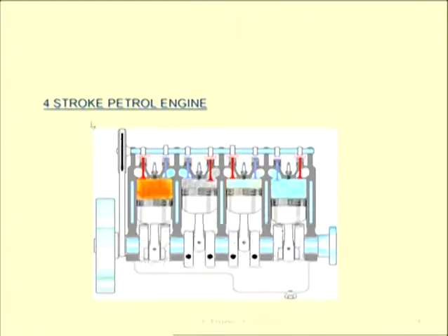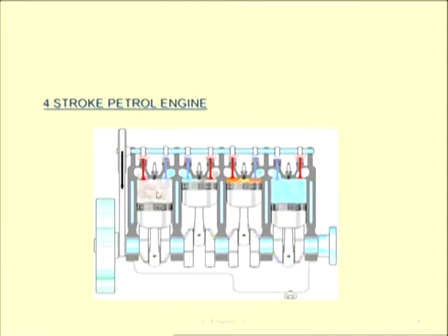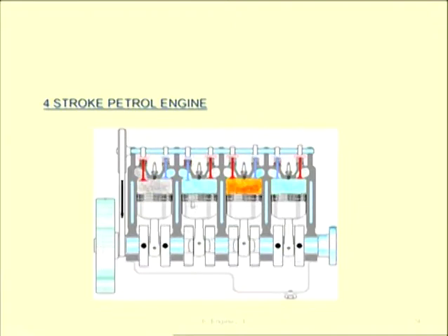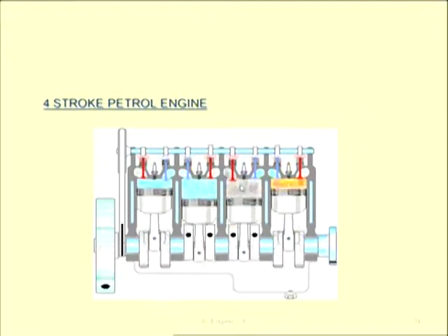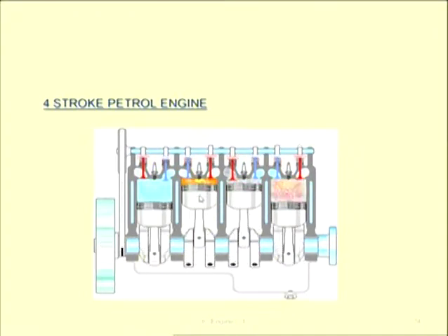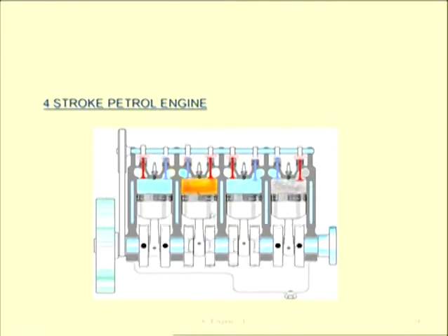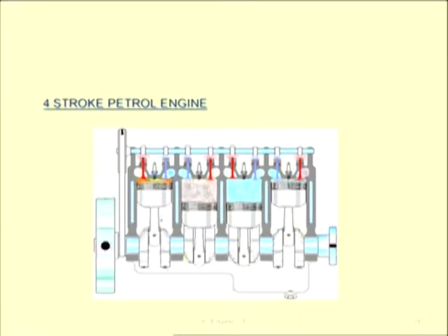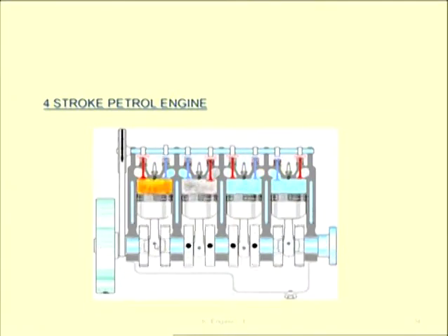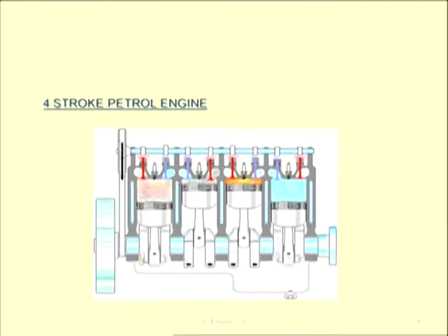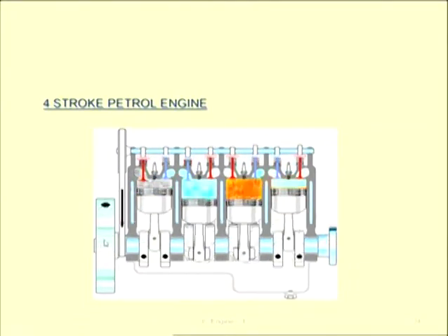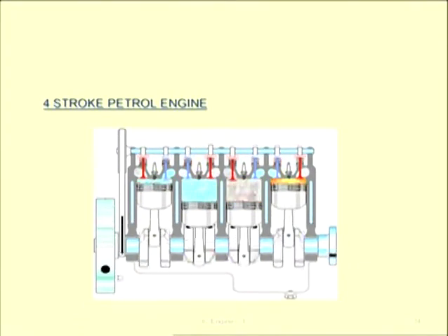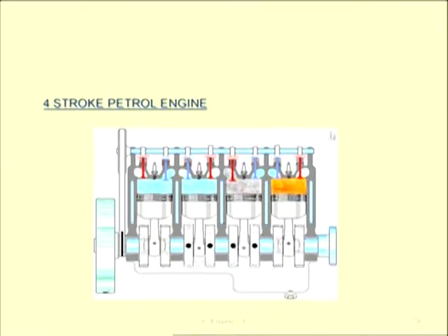You can see here when spark happens, it is having different cylinder options. So one, it starts here, then in a third. So we can take 1, 3rd, 4th and 2nd. So power stroke happens in this way: 1, 3, 4 and 2. This is the ratio. Now all is producing power in a different stroke. Here it is producing power while other is consuming. So all power output is converted into rotary motion of shaft, and it is connected with the crankshaft flywheel. So all the power is stored by flywheel, and in remaining strokes it is supplying energy to the piston.